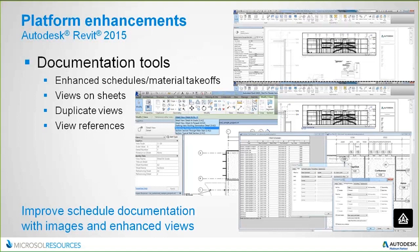And another one that's really nice is that when you duplicate views, it will not put the words copy of in front of the name of the view that you duplicated. Now it creates a new view with the same exact name with copy 1 or copy 2 at the end of it. So you don't have to go looking for it. It's going to show up in your browser in the same basic alphabetical location that it was before, and all you have to do is modify the name. And the same thing applies when you're talking about dependent views.